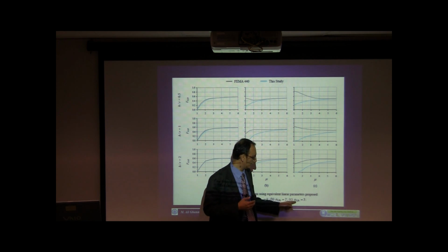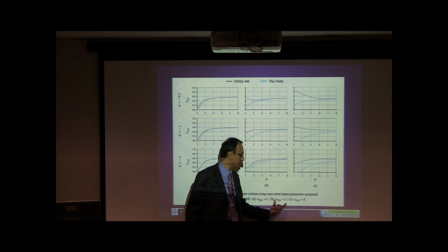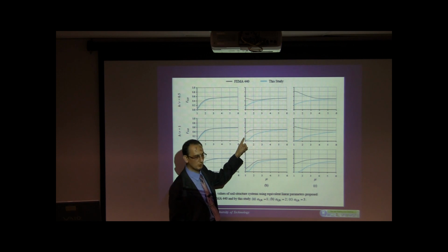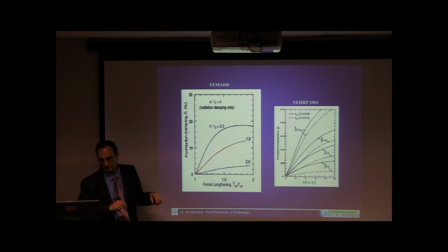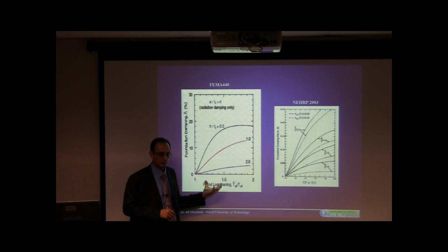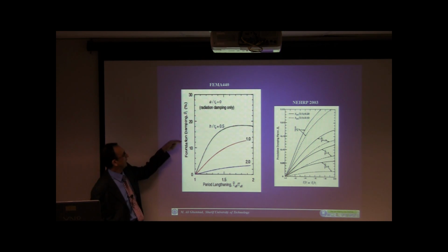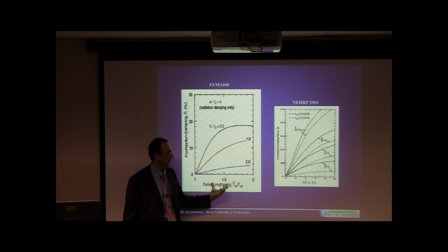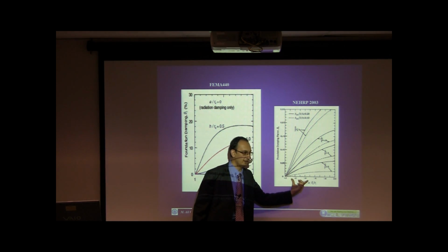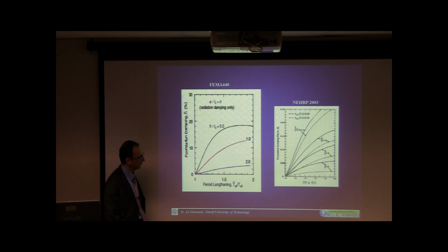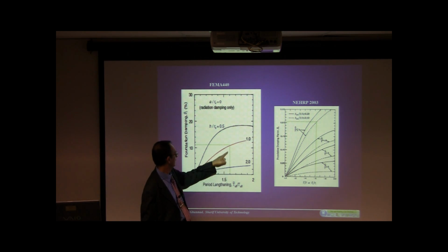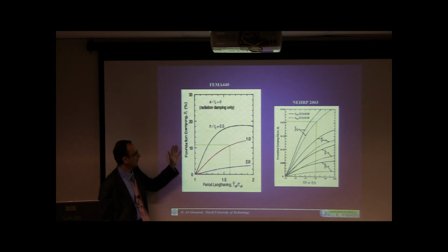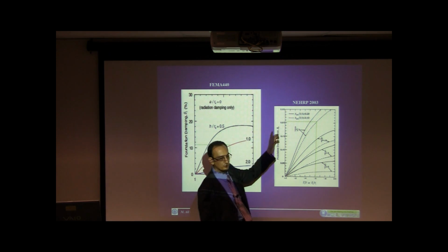And even if we ignore this case as an extreme case for A0 equals 2, we can start here. The main reason lies in this graph, that FEMA 440 gives to estimate the foundation damping, which can be compared with those in the ATC or NIHR. And you can see, for example, for one case, 1.6 as an example here, it leads to about 11% of damping. It's more than 20% damping here.